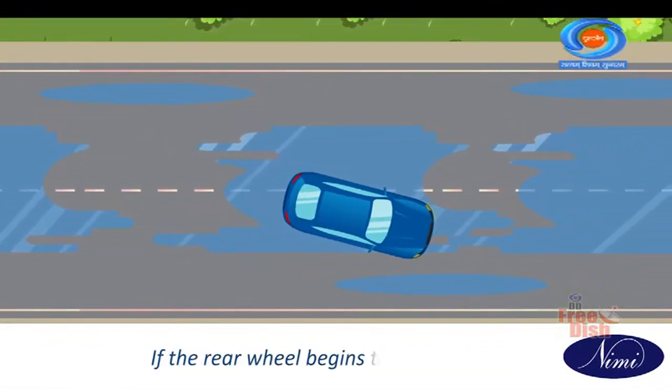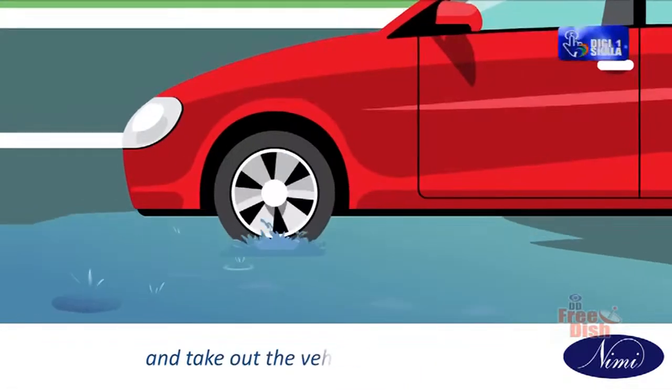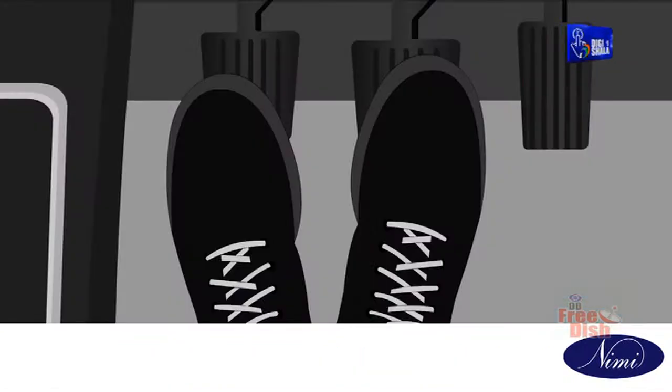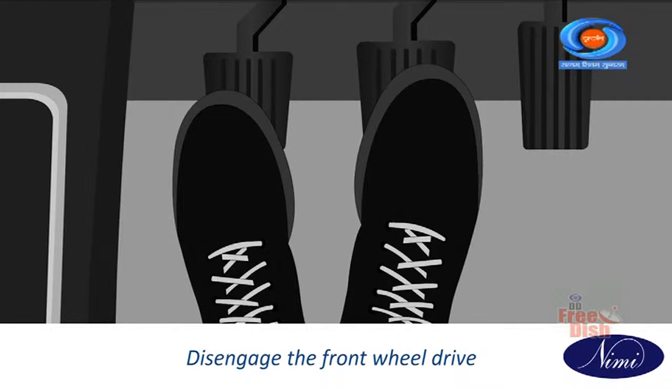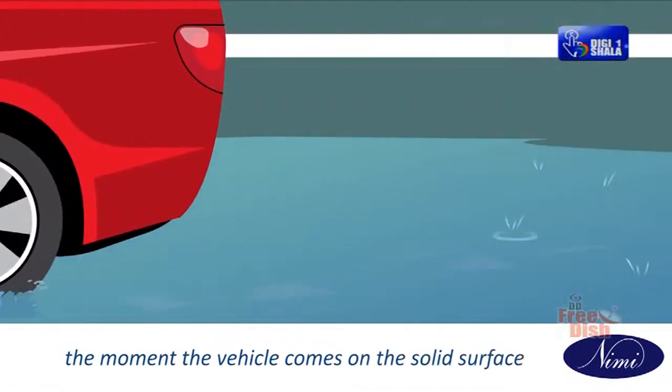If the rear wheel begins to spin, engage the front wheel drive and take the vehicle out of the sand using the first or second gear. Disengage the front wheel drive the moment the vehicle comes on the solid surface.